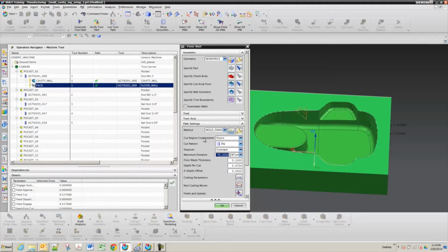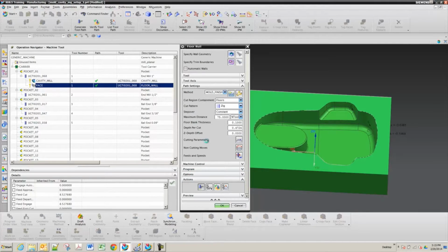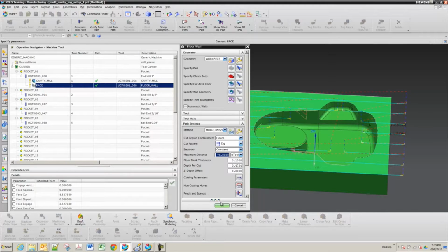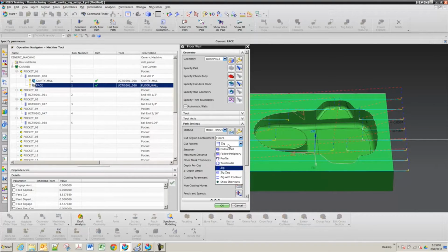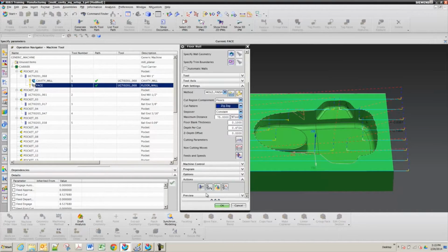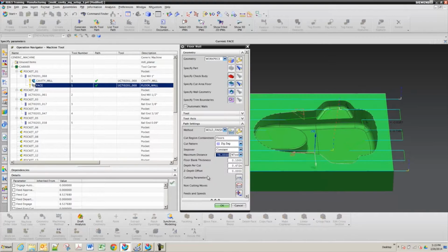It's in that area. It's set to some kind of inches on step over. See it under the pattern. You have pattern is zig. Step over constant, like 1/4 inch. So you can switch it back to either percentage or just set it to 3/4 of an inch, either way. Yeah, it did that on mine too.